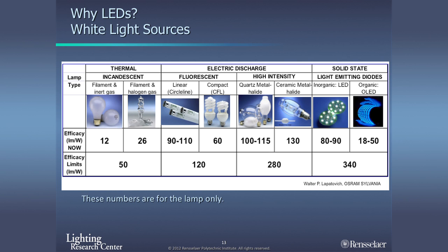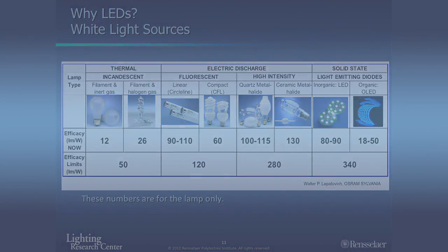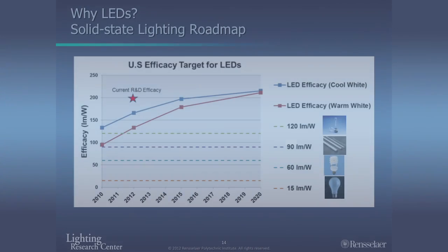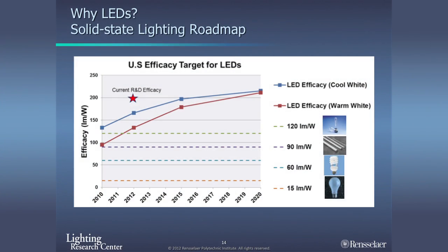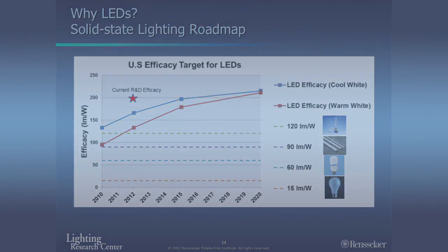Fluorescent is the main light source used. It typically, once it's installed, delivers well less than 100 lumens per watt. So we're going to see that. Now, where are we now? If you look at 2014, these are the efficacies that we see. We see about, for cool white LEDs, the cooler color temperature light sources, if you know what I mean by that, the whiter light sources above 4100 Kelvin, and that's a description of the whiteness of the light source for those of you who are not familiar with that.